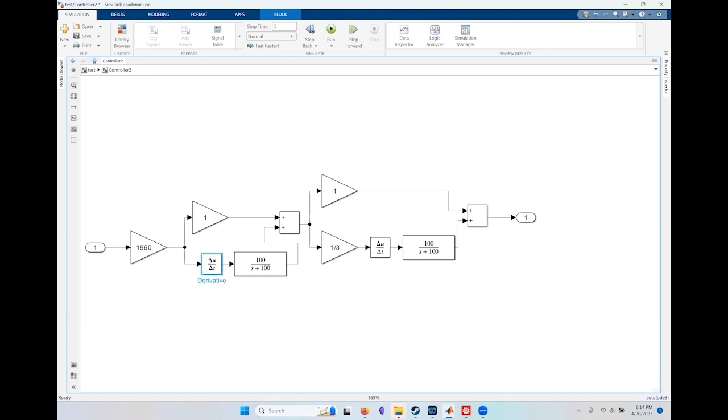The output of this differentiator for a step is going to be like an impulse. And this impulse doesn't show up when we do the exact analysis, because everything is taken into account all at once. However, when we do a simulation, everything is calculated step by step. Because nothing is solved all at once like in an analysis, in the initial steps some impulse is going to show up that shouldn't show up, right? So you're going to get an erroneous, incorrect response.